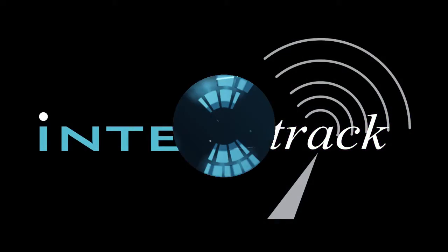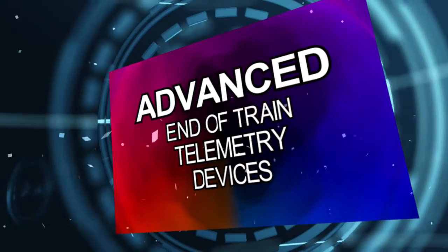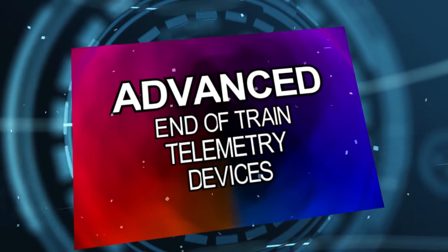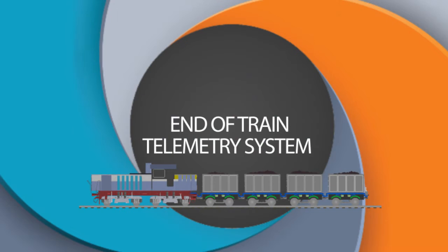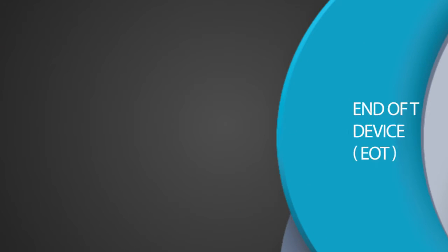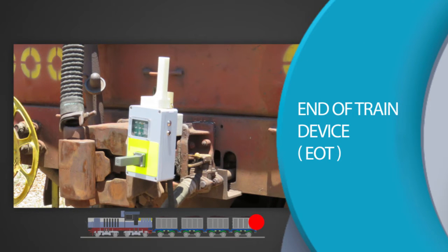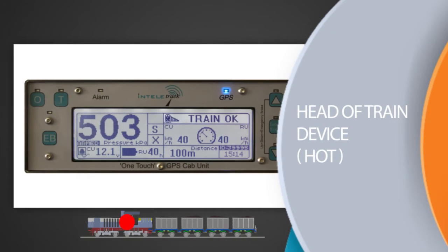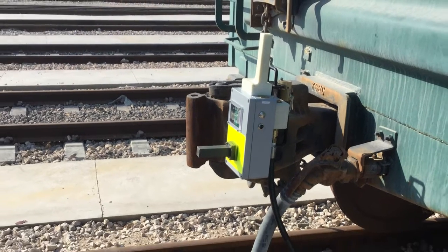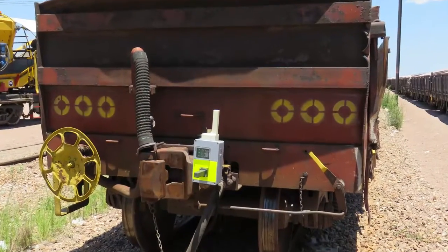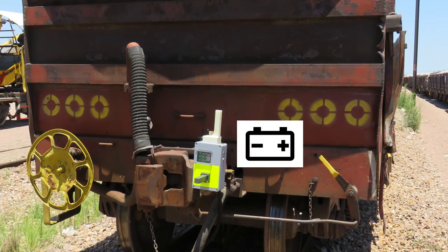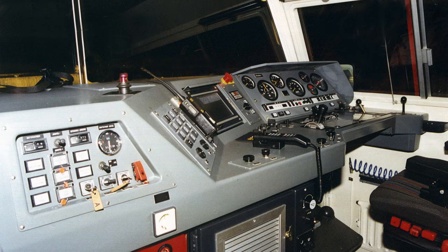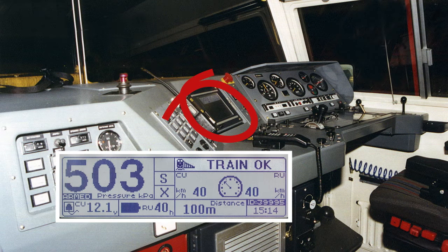This video will provide more detail on what our advanced end-of-train telemetry devices have to offer. An end-of-train telemetry system consists of an end-of-train device, commonly referred to as an EOT, and a head-of-train device, commonly referred to as an HOT. The EOT is mounted on the outside at the rear end of the last wagon of the train and is battery-powered. The HOT, on the other hand, is installed in the cab of the locomotive, where it is easily accessible and visible to the driver of the train.